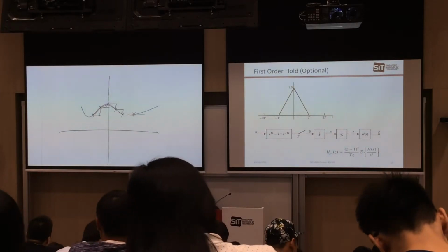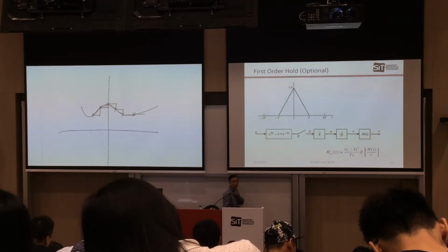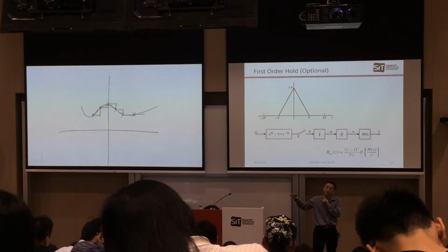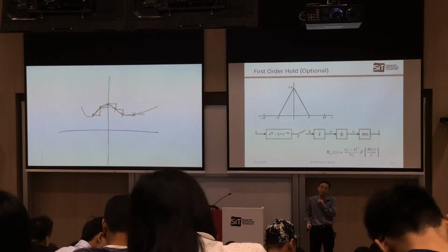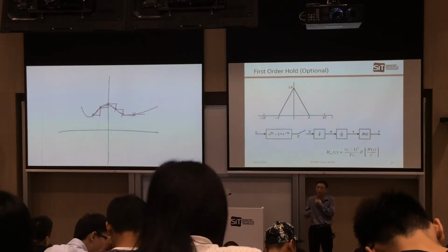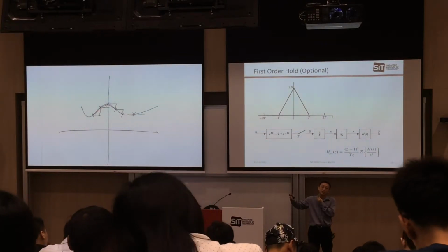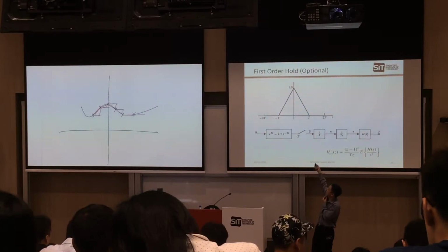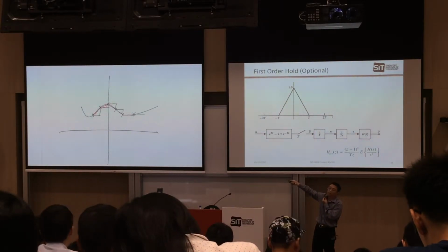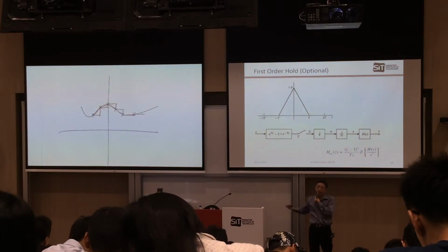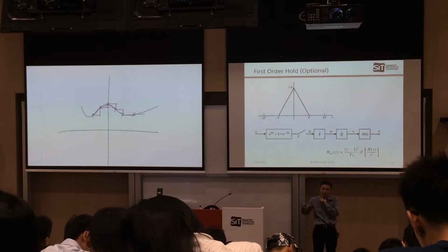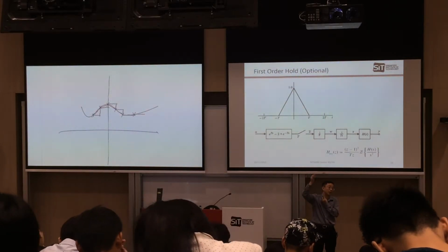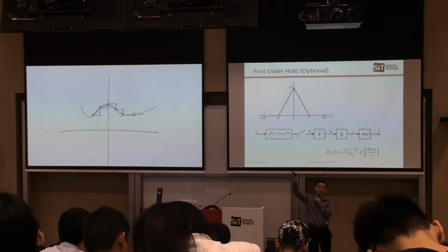When your sampling time is big, meaning when your sampling frequency is low, definitely you can see your first order will be much closer than your zero order hold, right? So this is very simple, like your zero order hold, you just hold and remain the same as the previous one, right? No contribution on it. But the first order hold, at least you have considered your current and your next point linked together, right? And usually your current data and your next point will suddenly jump. If you're doing the zero order hold, it's a sudden jump, right? But your first order is gradually linked, right?